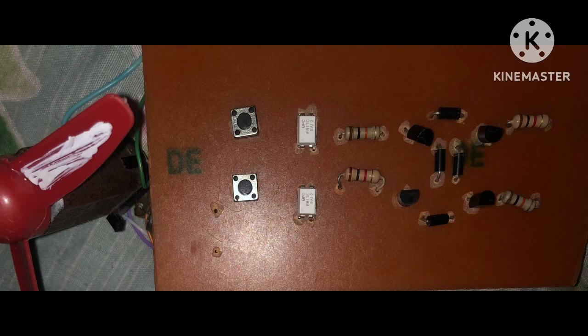After that step, when the PCB sheet comes to its normal position, then FeCl3 chemical is used to remove the copper from the other side. Instead, the tracks of the circuit remain. After that, when the tracks remain, clean the circuit with petrol or something else. Then the next step is drilling.